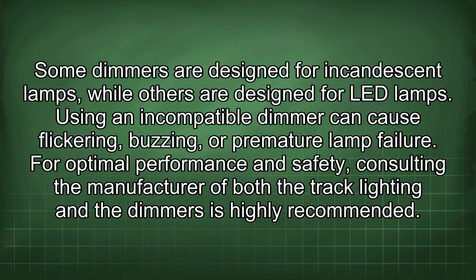Some dimmers are designed for incandescent lamps, while others are designed for LED lamps. Using an incompatible dimmer can cause flickering, buzzing, or premature lamp failure. For optimal performance and safety, consulting the manufacturer of both the track lighting and the dimmers is highly recommended.